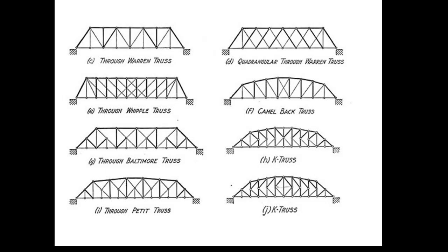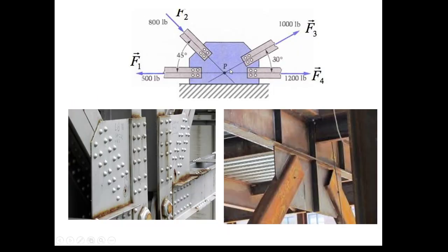Okay? And you know, we already talked about it. To be able to prevent having bending moments, bending effects, the lines of action of the forces are to be transmitted from one joint to the other joint. Okay? In other words, the forces exerted by the members at the joint are to pass through the same point. In other words, the lines of action of the forces are to intersect at a single point. To be able to have the forces such that their lines of action intersect each other at a single point, yes,